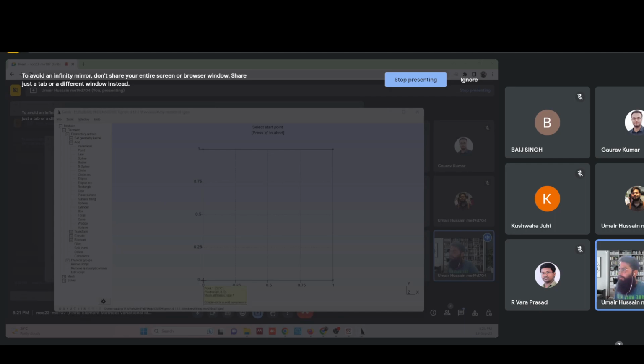Then we add line, select first point, then select second point. Then we repeat that for each pair of points. We got a line here. We press Q again. Now next we define a plane surface. Select the surface boundary. If there's supposed to be any hole in the surface, we have to select the hole, but we don't have any hole here, so we press E.